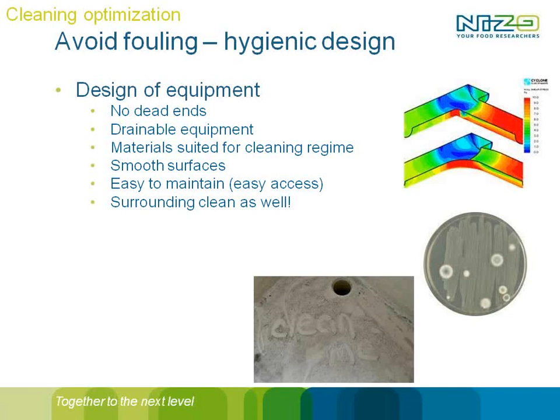Try to avoid, for example, a steel which is corroded by your cleaning agent, because then your surface will become worse. So be careful with the cleaning agents you use, and take care that the materials of your equipment can withstand it.